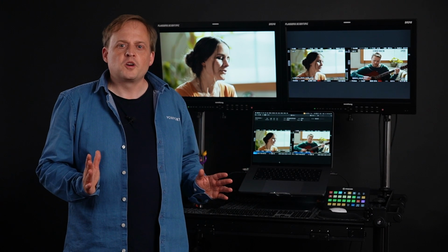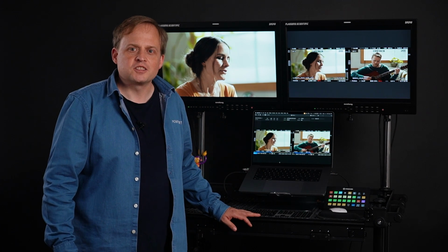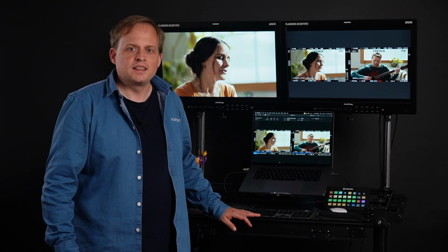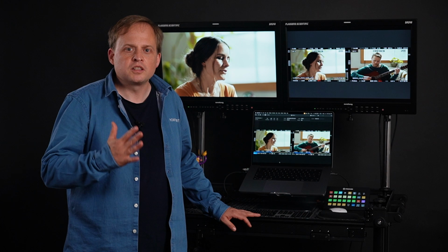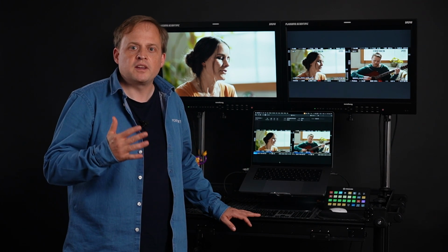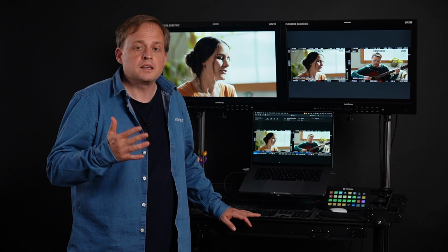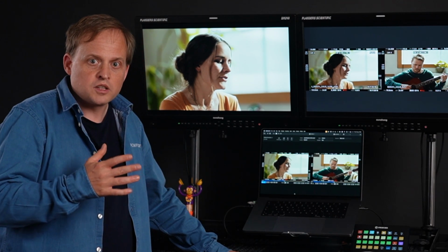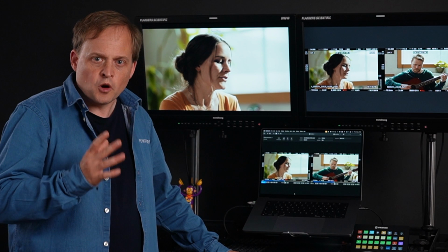So far, we only worked within the main view window layout. Time to check out the multi-view layouts. One of your responsibilities as a playback operator is monitoring all camera feeds, ensuring all signals are okay, having an additional pair of eyes continuity-wise, etc. The multi-view is primarily designed for operators with no SDI monitor who need to operate on a small screen such as a MacBook Pro 16-inch. It helps you to focus on a current task by eliminating all irrelevant options in the UI for a moment.